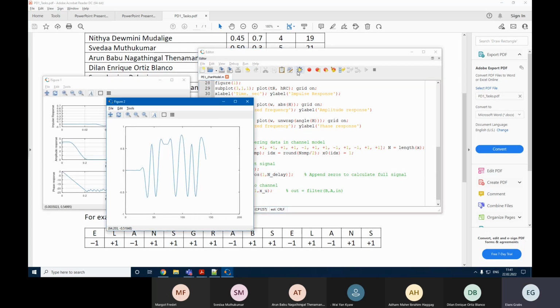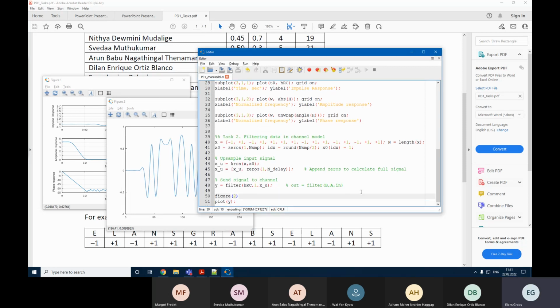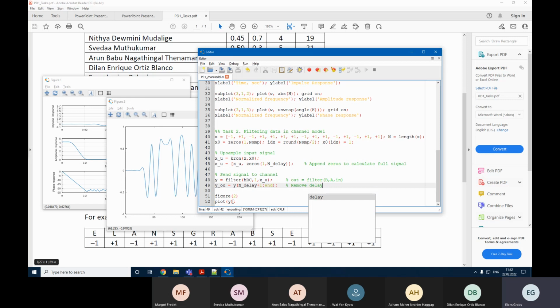Okay. So if we calculate it now, you can see that currently we have this signal calculated completely, but we still have this delay. Now we need to cut off this part of the signal. Accordingly, we are going to read our signal starting from n delay + 1 value up to the final ending value, right? So here we trim delay values. So basically remove delay, what we are wanting to do. And now we plot this output signal right here.